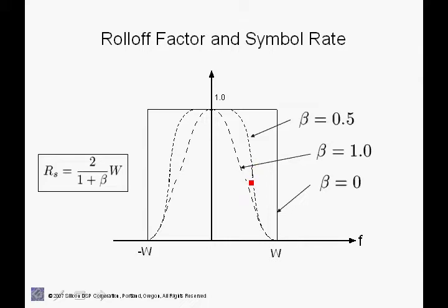This basically shows that we can achieve higher throughput using different values of beta, and this comes at a cost, as we will show when we look at the impulse response for the various raised cosine filters. This is to be expected: for lower values of beta, even though we get higher throughput, in the time domain we have to worry about clock jitter, and the fact that if we have clock jitter we can introduce intersymbol interference if beta is small.